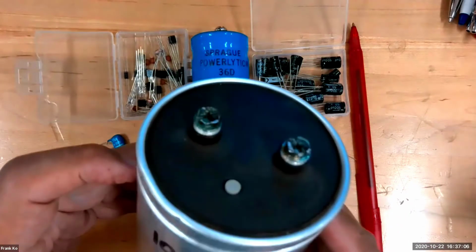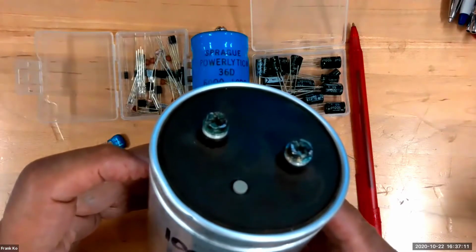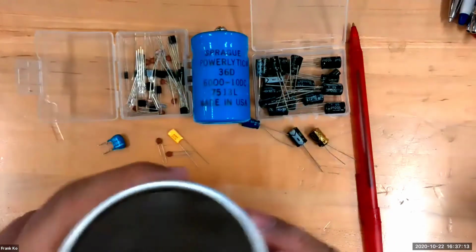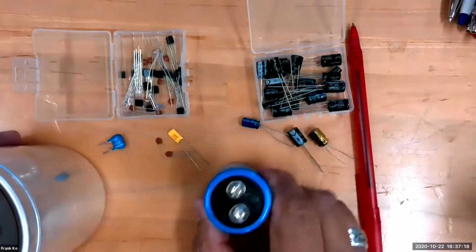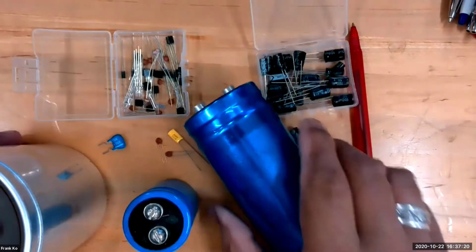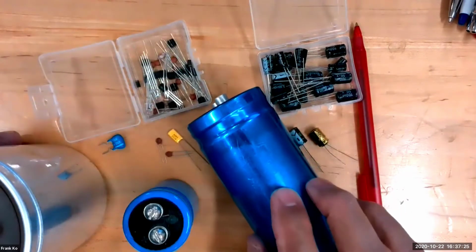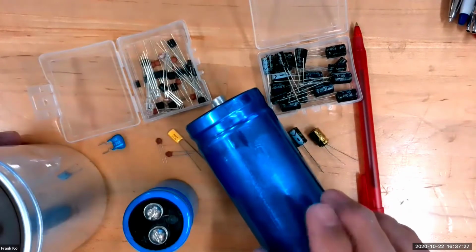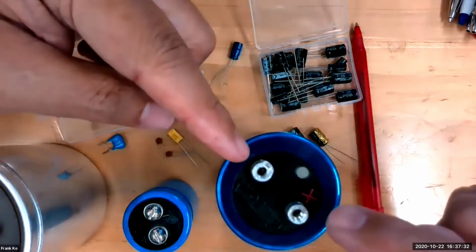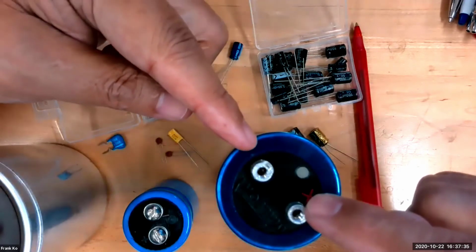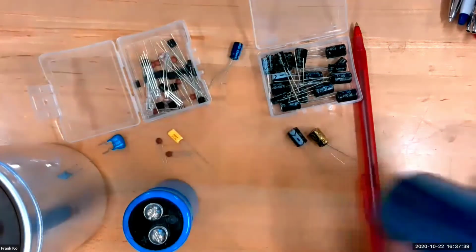Capacitors not only hold charge, they can store that charge for a really long amount of time. So that means when you, as a technician, come across capacitors in a lab, in a work situation, at a factory, you don't know when it was previously charged. You don't know how much charge there is on there. So since you don't know, are you going to arbitrarily touch these two terminals with your fingers? Absolutely not, because the spark is going to be harmful to you.